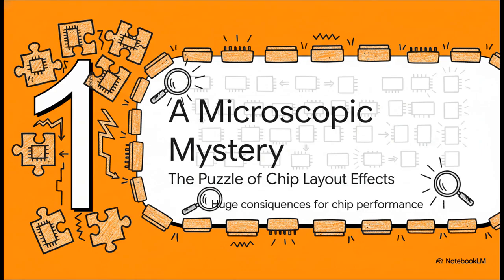So here we are at section 1, a microscopic mystery. And our story really kicks off with this puzzle, one that has massive consequences for how well our chips perform. It's all about something called local layout effects, or LLEs for short. And the big idea here is pretty simple, actually. A transistor doesn't live in a vacuum. Its behavior isn't just about its own specs. It's about who its neighbors are.